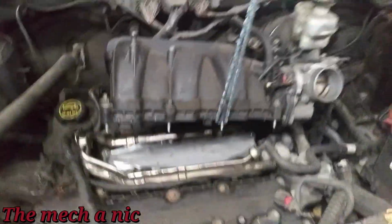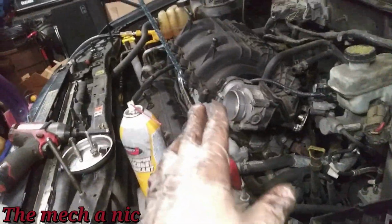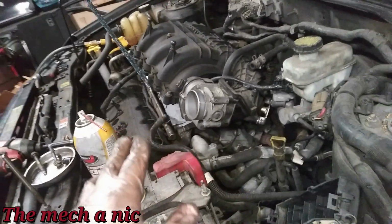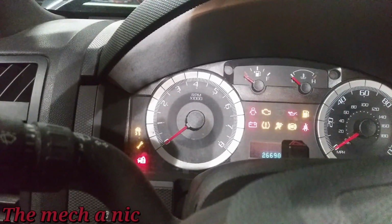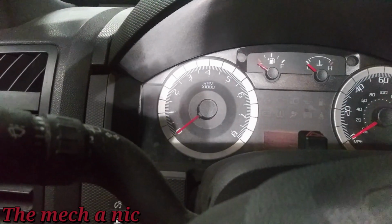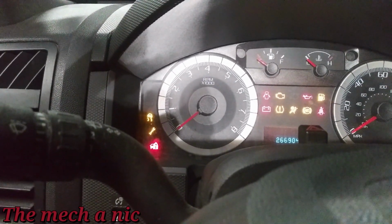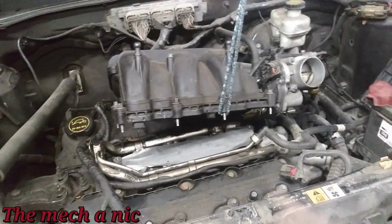What I'm going to do now, before I start putting all this together, I'm going to go ahead and turn the key and let the fuel pump build up some pressure. I want to make sure I don't have any leaks at any of these fuel injectors before I start putting all of this together. So far everything looks good. Alright, so I'm going to go ahead and finish putting all of this back together.